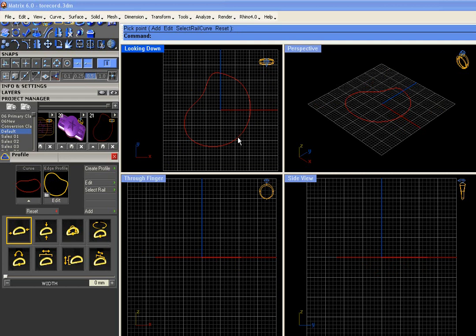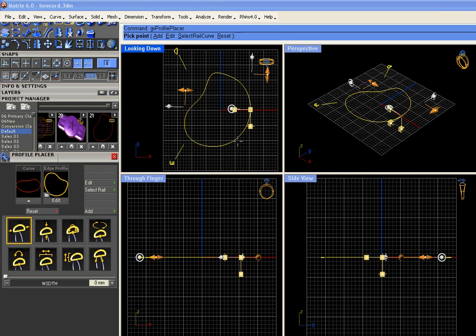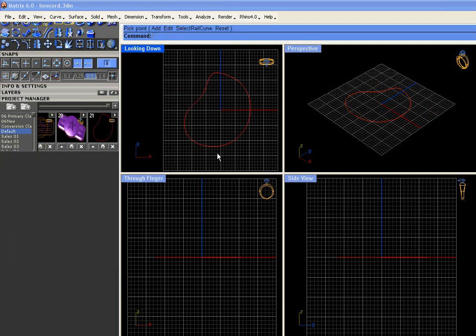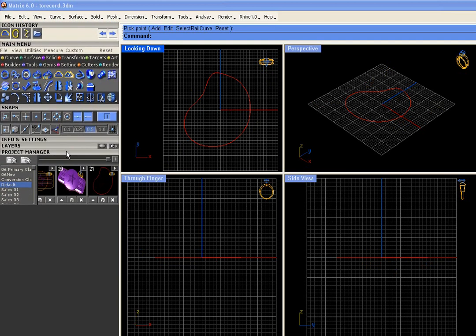If we hadn't done that, it's possible also to select the curve, press F6, and choose MSR. Even before we put it into this builder, you'll get all the handles, so any closed curve can be made into a profile using this tool. Simply press enter to end the command and turn off the handles. And once it has those handles attached to it one time, it's all ready to be made into a bezel.